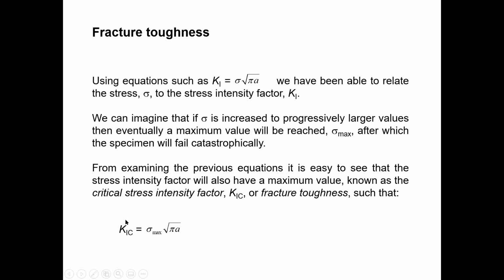The KIC, the alternative name is fracture toughness. Okay, critical stress intensity factor, KIC, is the fracture toughness. So what is fracture toughness? It is the critical stress intensity factor. But you need to substitute sigma maximum here. So we apply the maximum stress, but in that particular example we are not going to increase the stress, so same stress. We are going to find out the maximum A value, or critical A value, we can put in the element. So fracture toughness and critical stress intensity factor are the same thing.